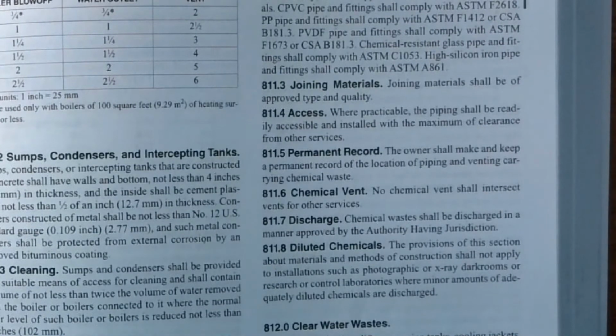And the reason for that is the corrosiveness of that chemical waste. If the waste has corrosive materials, as acidic or whatever, then as it's being vented and as that air is moving through while the drain is going out, it could carry particles of waste through the vent system and actually start to break down and deteriorate your regular normal sanitary systems. So they have to be separate.